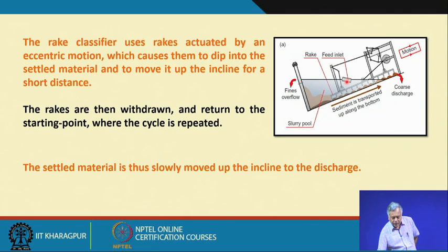The coarser particles will try to settle immediately at the bottom, and because you are pouring in continuously, the water will start overflowing. Along with that, the relatively finer particles will also be removed from this volume space, and then you are collecting them. That is why it is said the fines overflow along with a large volume of water.